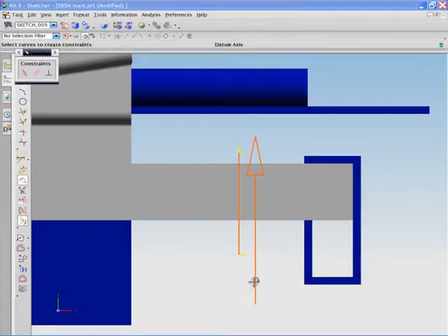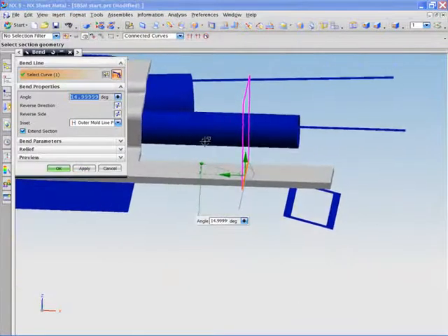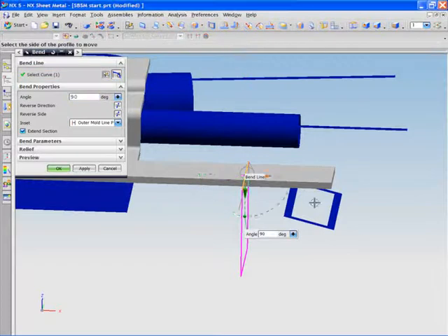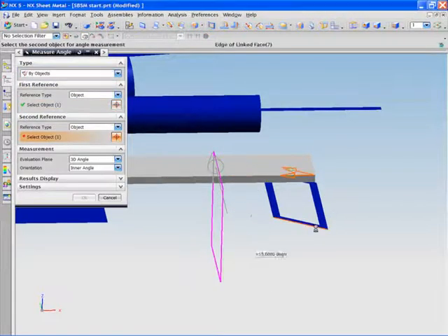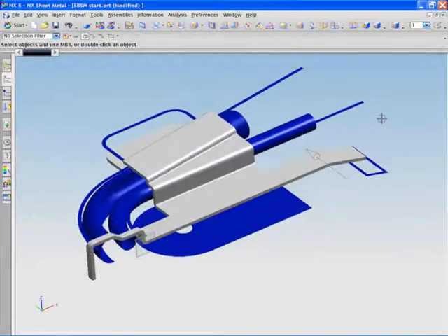The final tab will now be added to the fixture holes created. Again, the reference geometry will be used to assist the creation of these. To make sure of a good fit, the tab created needs to be modified and a bend added. This can be easily added retrospectively.